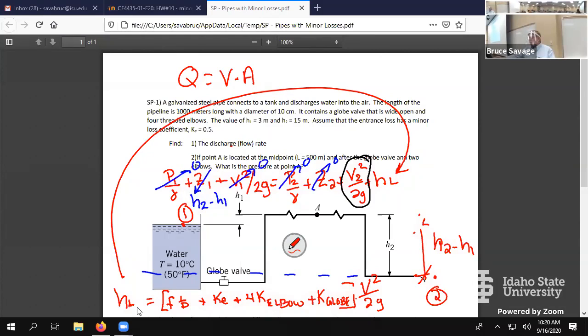You can put it in this form right here and solve for the velocity. That's actually easier for the Reynolds number, because it's velocity times diameter divided by viscosity. Once you get velocity converged, multiply it by the area, and boom, there you got your flow rate. What I'm saying is, you've only got one term there, velocity squared. The one term you don't have in the first equation is velocity squared, the same one down there in the head loss equation. Are they not the same velocity?